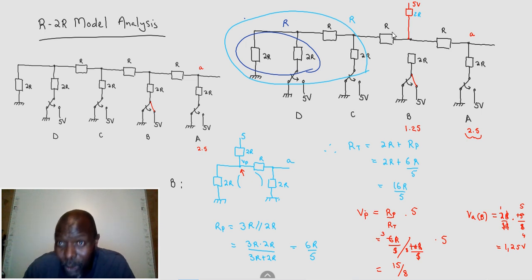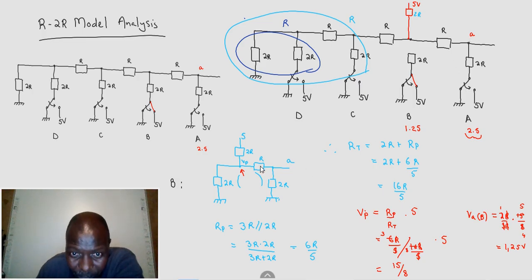Now we've got 2R, and then this 2R is going to ground there, and it's branching there. This other pair is going to ground. So this set and that set are parallel. So 2R is parallel to 3R. But we want the voltage there, hence the step. So we started here by showing what this reduced to: 2R parallel to 3R, which is that.